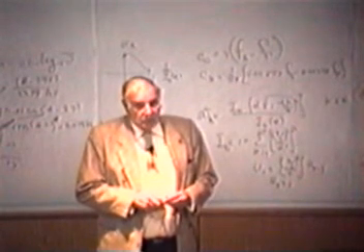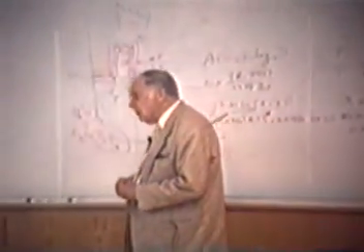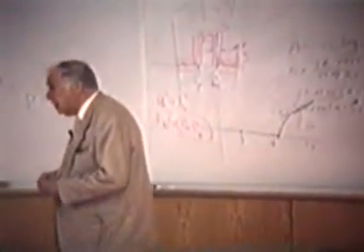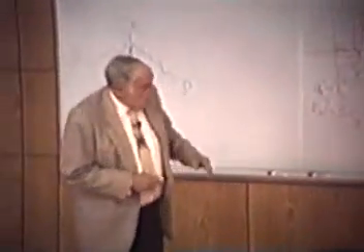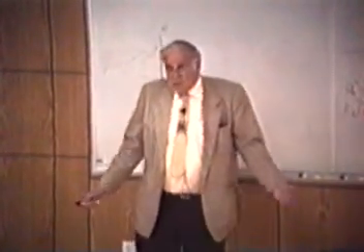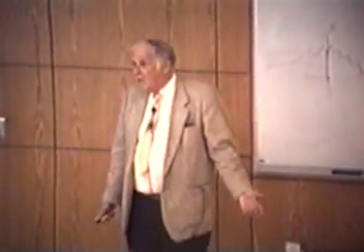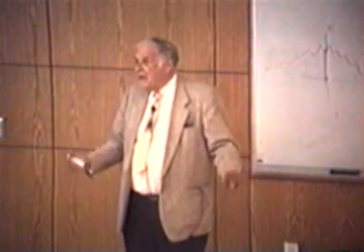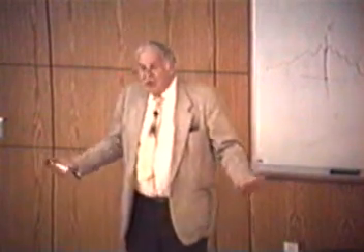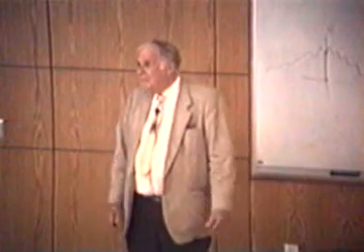It's not the spectrum. Because while Fourier series is linear and you can add two signals to get the sum, the spectra, which involves squares, the spectra of the sum is not the sum of the spectra, right? For example, take a signal, an exact negative of it. The sum will be 0, but the spectra will both be the same.